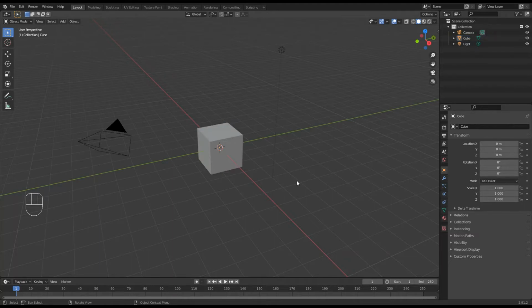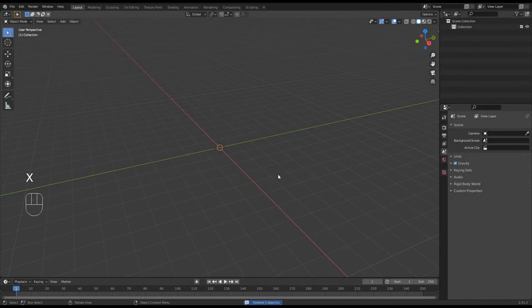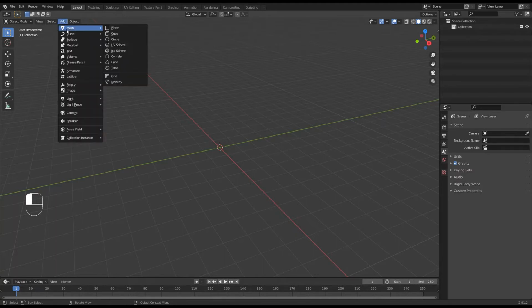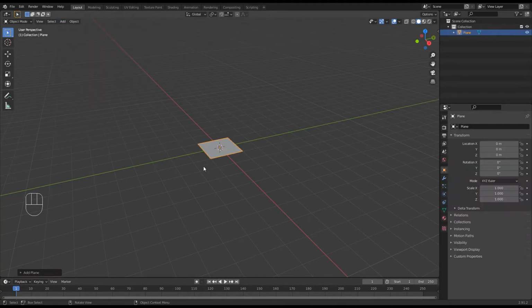Right, so the first thing here is, again, I don't want any of these items, so clicking in the workspace, then pressing the key A for all. That selects everything in the 3D area, and then press X for delete. Right. So now what I want to do is start with a point and then draw a line and then build faces onto that line.